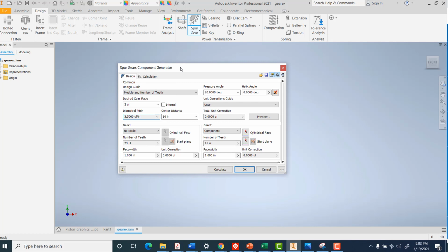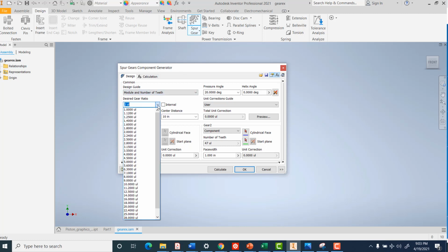There's actually a lot that goes into gears of how the force is coming into play and what the gear ratio is to get the mechanical advantage you want. The gear ratio tells you the mechanical advantage. So you have a small gear that's going to be spinning like mad, a large gear that's going slow, and what you lose in speed, you gain in force. So you can think of your bike gears and how those work. If you're pedaling like mad, but you're not going very fast, you have a small force and you're going a slow speed.